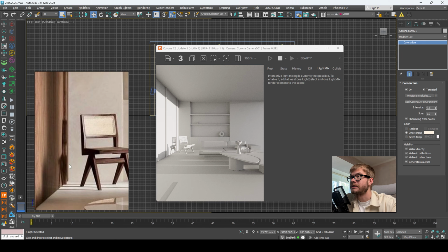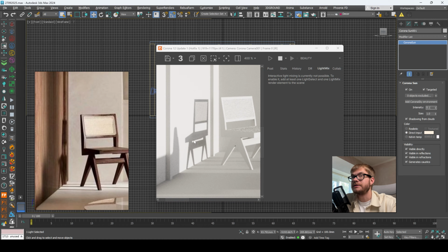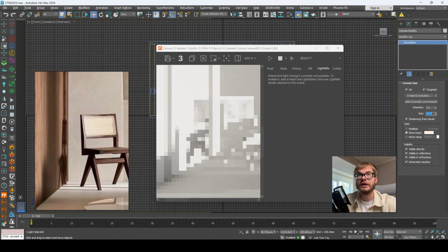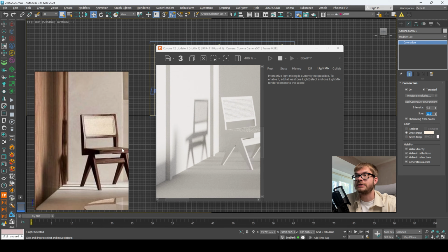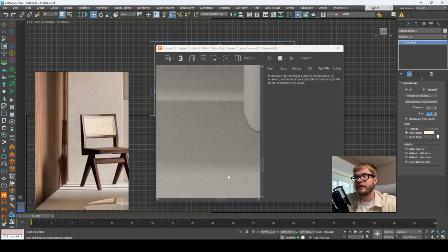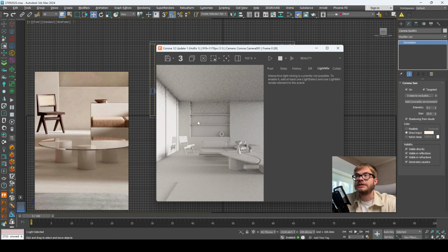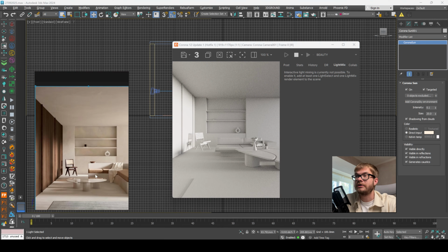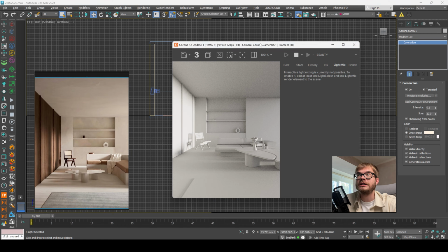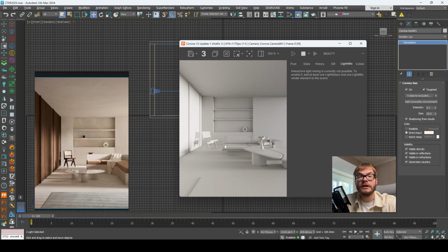Right here we got our shadow pretty crushed. So actually it's not so detailed. We need more blur to blur our sun. Indicate here 10. In this case, shadow will appear less detailed and smoother, as you can see right here. Actually, we can make it even larger. Nice. And now let's manipulate our Corona sky and sun to match the lighting in our scene with our reference.